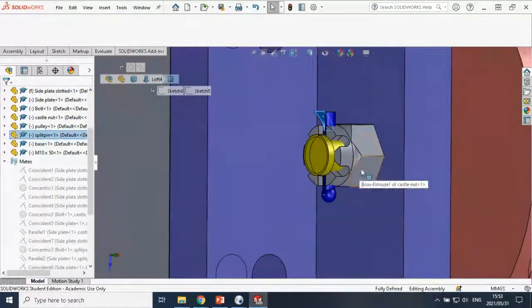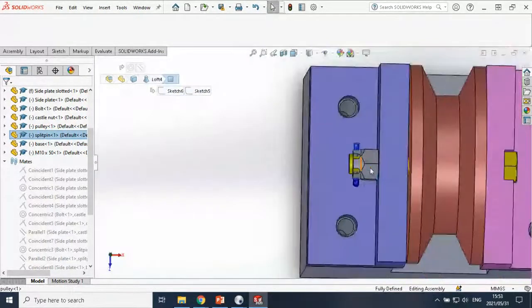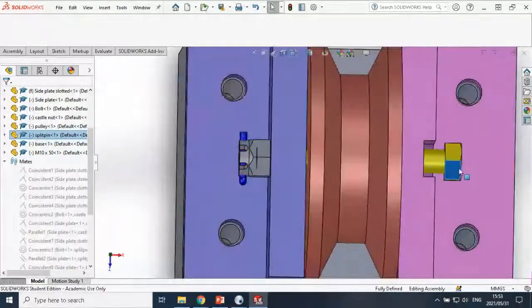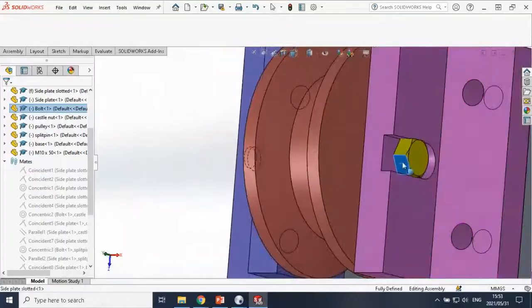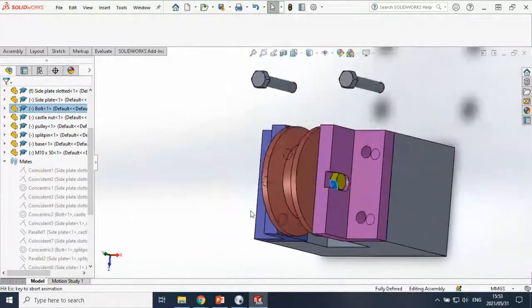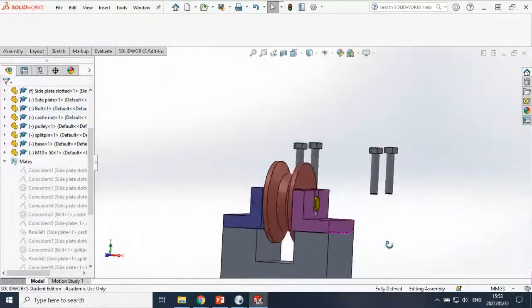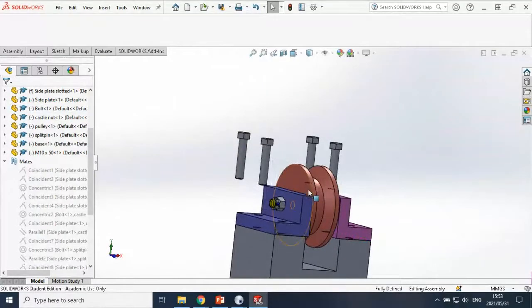So that split pin will stop the castle nut from coming loose, which means that yellow bolt will never be able to pull out towards the right hand side like I did it now. And this groove will stop the bolt's head from ever being able to spin. So basically, the way I did it now forces this wheel to never be able to turn the bolt.